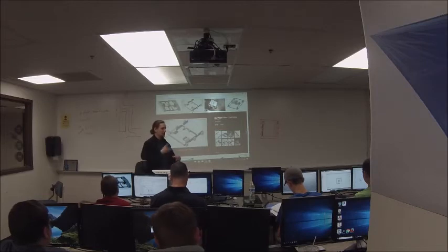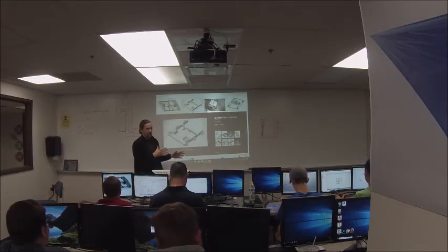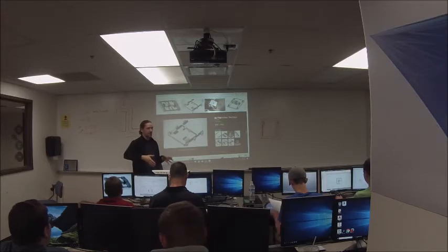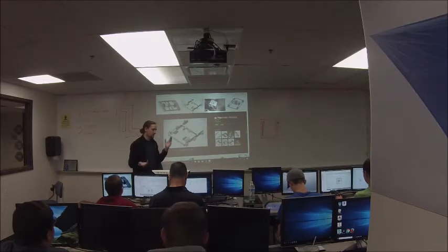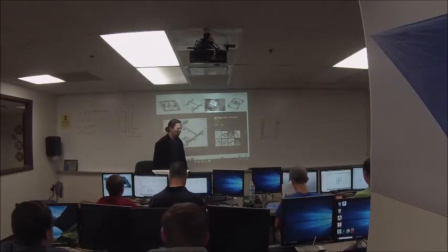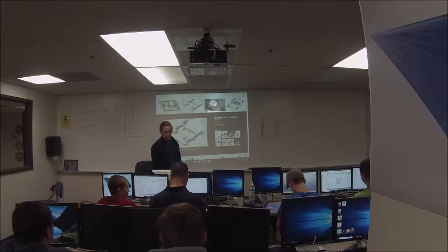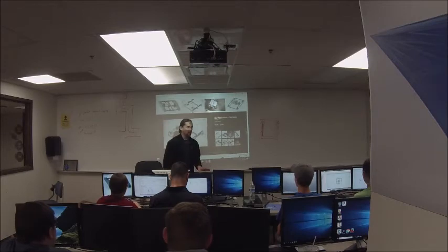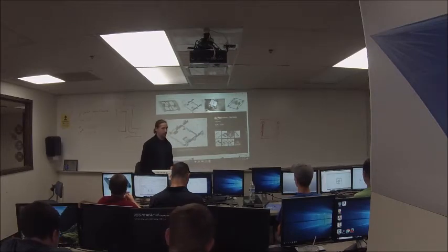That sideways module is the only thing stopping the robot from free sliding sideways, because the Omni wheels can also slide sideways freely without any ability to stop themselves. So you want to run an H drive on a flat field, because it just doesn't work on anything else.